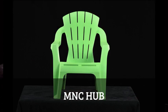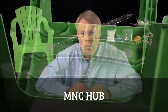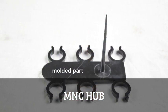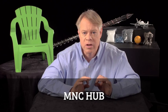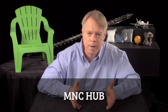For example, this chair, on its bottom, has an array of witness marks. When the part drops from the mold, an operator has to remove the sprue, that section of plastic that connected the injection unit to the mold. Sprues are manually twisted or cut off the part. Sprues are attached to objects only in molds that make a single part at a time, like a chair.